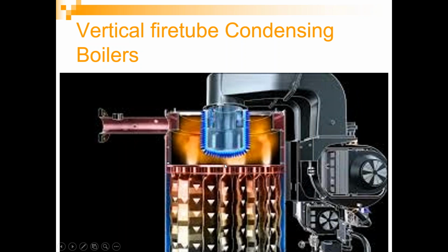One of the downsides of the stainless steel fire tube boilers that are being rushed to market by some of the manufacturers out there is they're not field repairable. If you get a deformation or a crack in the top of this tube sheet in a stainless steel vertical fire tube type boiler, you have to throw the boiler away and start over. You cannot repair it in the field. It doesn't lend itself to that type of depth.